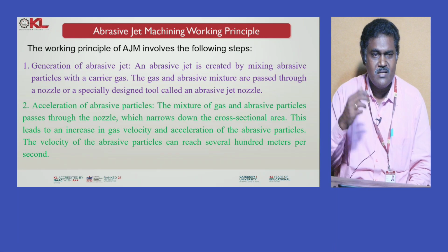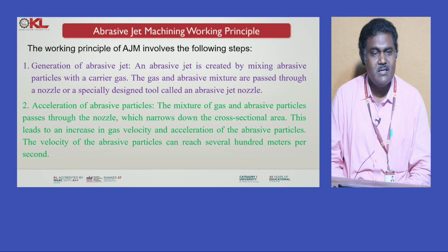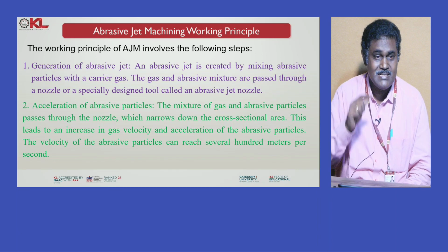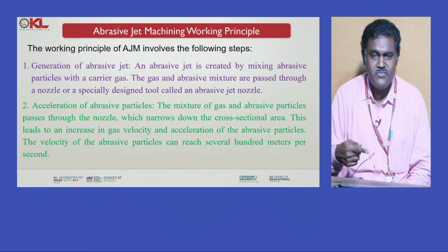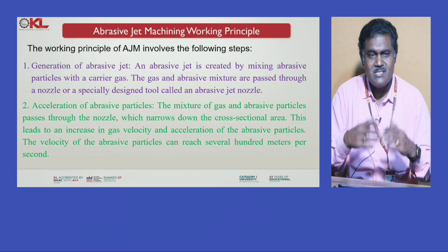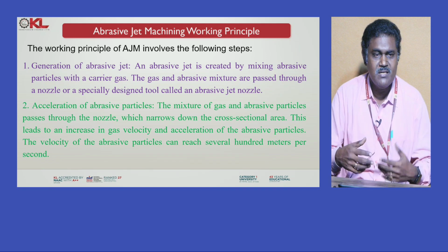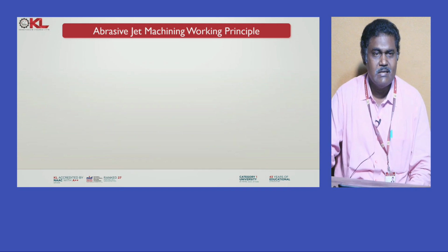Next, acceleration of abrasive particles. The mixture of gas and abrasive particles passes through the nozzle, which narrows down the cross-sectional area. This leads to an increase in gas velocity and acceleration of the abrasive particles. The velocity of the abrasive particles can reach several hundred meters per second.